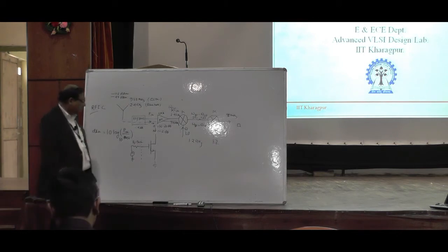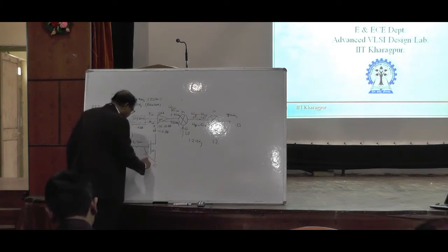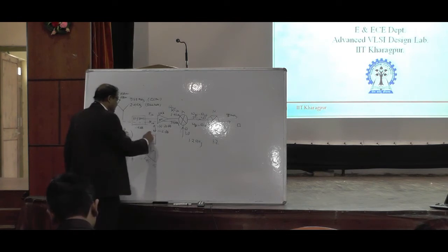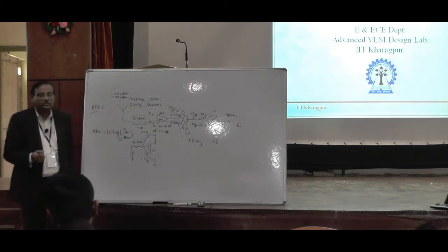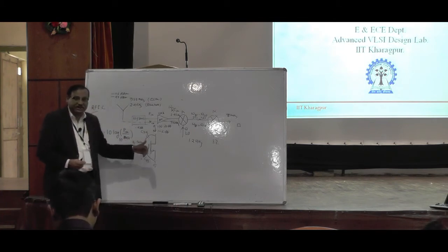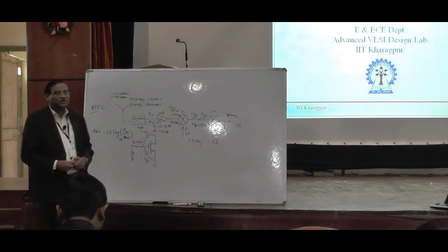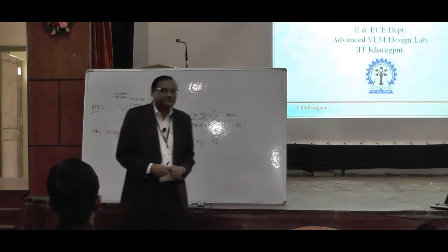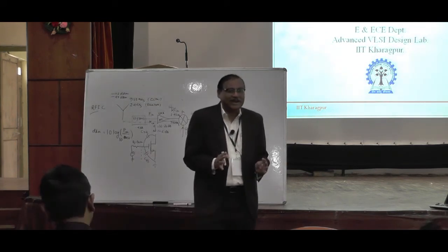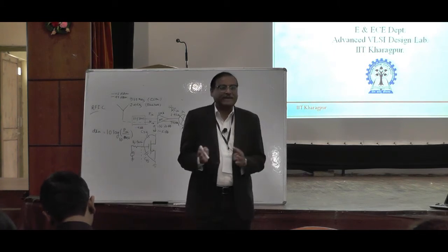Now with the transistor, at least you know there is a gate-to-source capacitance, CGS, and at least you know there is a capacitance, CDG. Yes or no? But if you look, the right side is purely capacitive in nature and the left side is purely resistive in nature. So under any circumstances it is not going to match. So the first part, the LNA design, is at stake. I want to have gain, but my input signal is likely to reflect back.